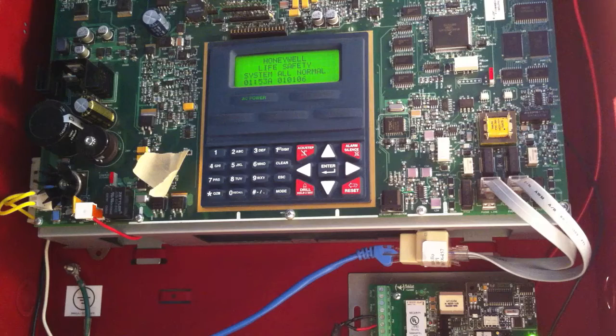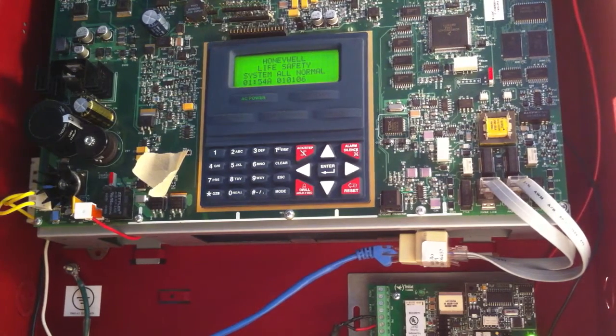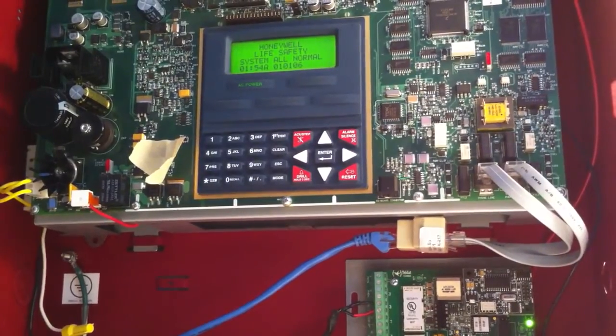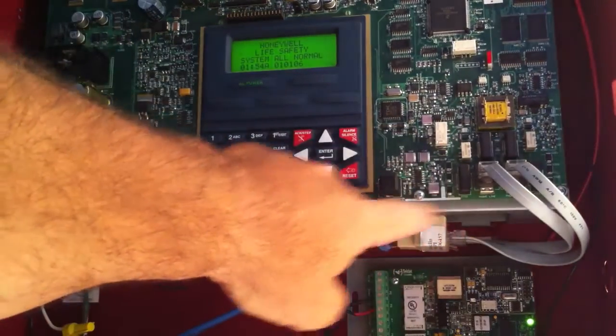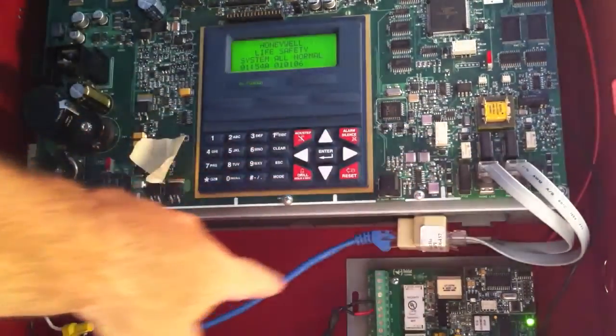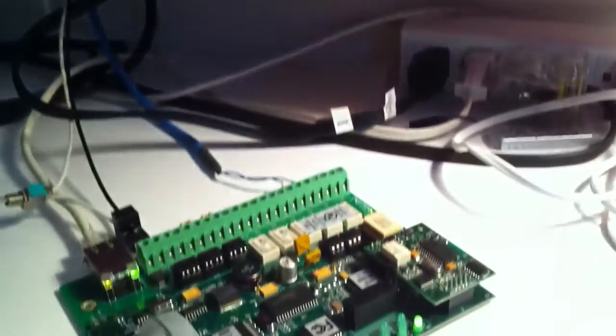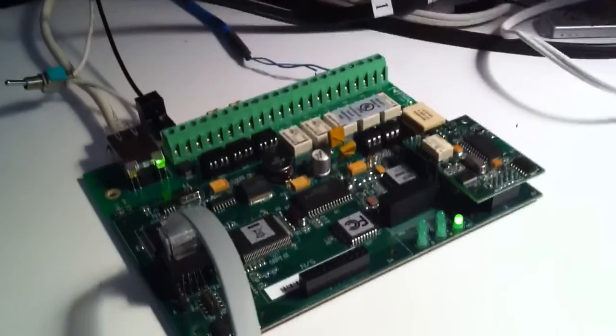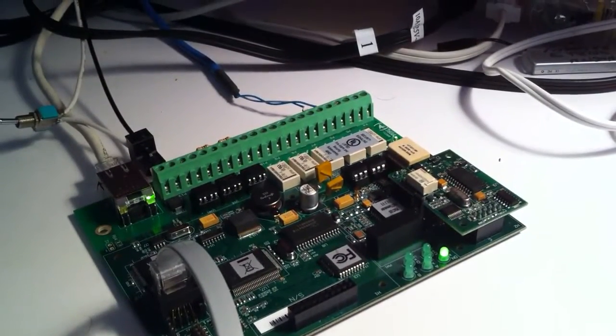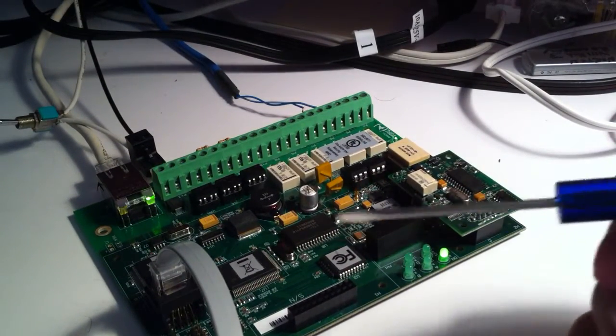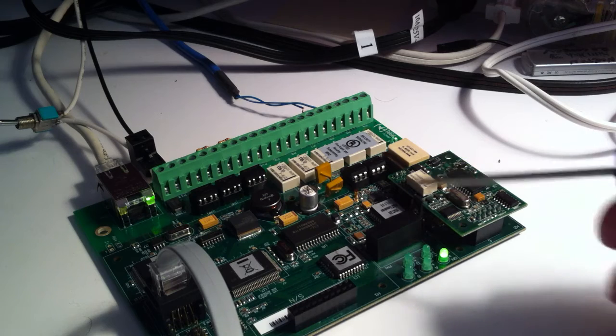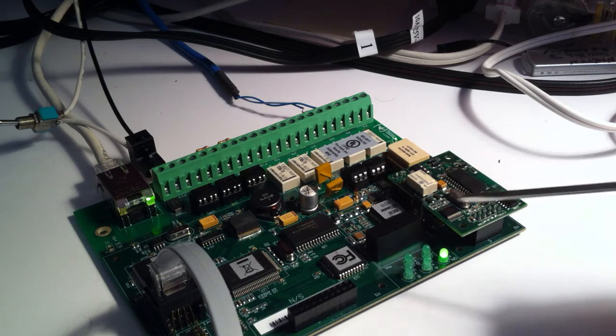Today we're going to look at upload download through the internet and how you do that. Here I have an MS9050 UD and an IP-DAC to UD connected via the two incoming telephone ports. To do upload download, you can't use just an IP-DAC2. You need the 2UD, which includes this plug-in modem.